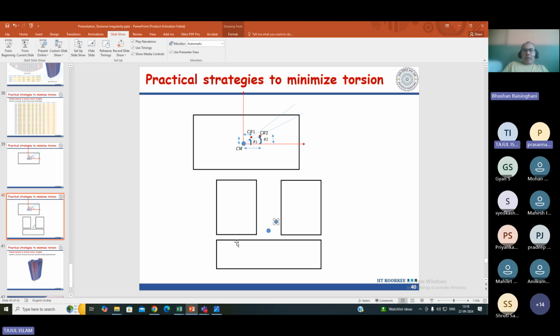Yeah, that's what I initially suggested, to have the joints instead of connecting with rigid members. Because if you combine the three, then you have to go for the time history analysis. There is no other option, and that is the only way out of it. Because it is not approved by the code, so you have to prove it, and that you can do only by the time history analysis. Okay, sir.